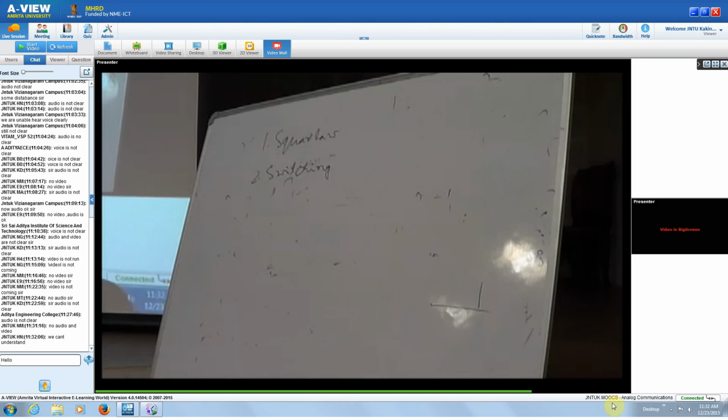Then the third element that we require is a band pass filter or a tuned circuit. A band pass filter, because we have to eliminate other frequencies except these two sidebands along with the carrier signal. So we are going to have a band pass filter tuned to our center frequency. So you are having a tuned circuit. You may be having a single tuned circuit or a double tuned circuit.